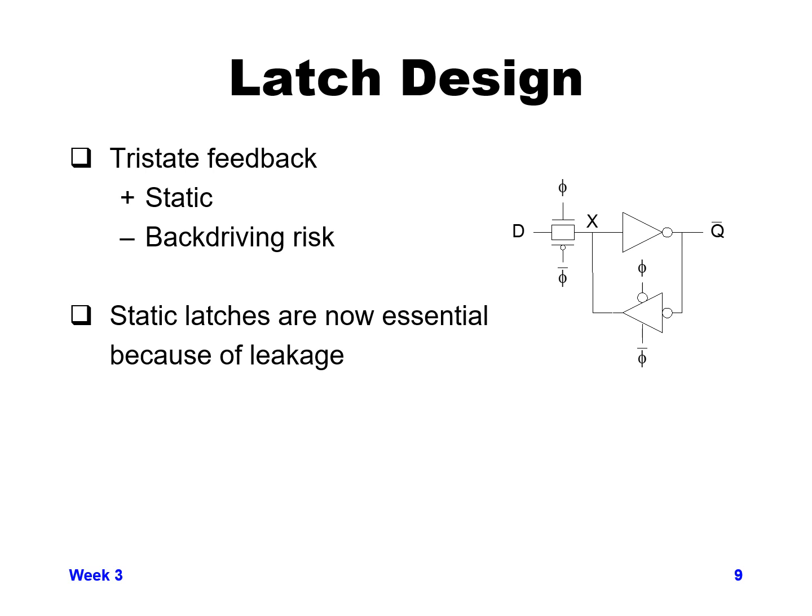Again though, this adds a little bit more to your backdriving risk. When you open the pass gate at the input to this latch, the value that's in X is going to try and drive back and override the value of D. This is made worse by the fact that we now have this feedback device that's actively driving X. So we need to make sure that whatever is driving the D node, the input data node, is definitely stronger than the feedback element inside the latch.